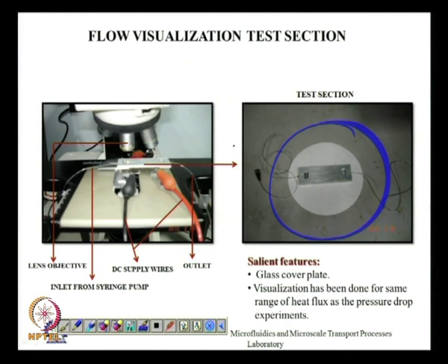Okay, an aluminum channel, and on the aluminum channel, using a milling process, you create thin channels. The channels are still hundreds of microns in size, about 75 to 150 microns, and the milling process was varied so as to get different surface roughnesses. We wanted to see how surface roughness will help in the bubble formation.